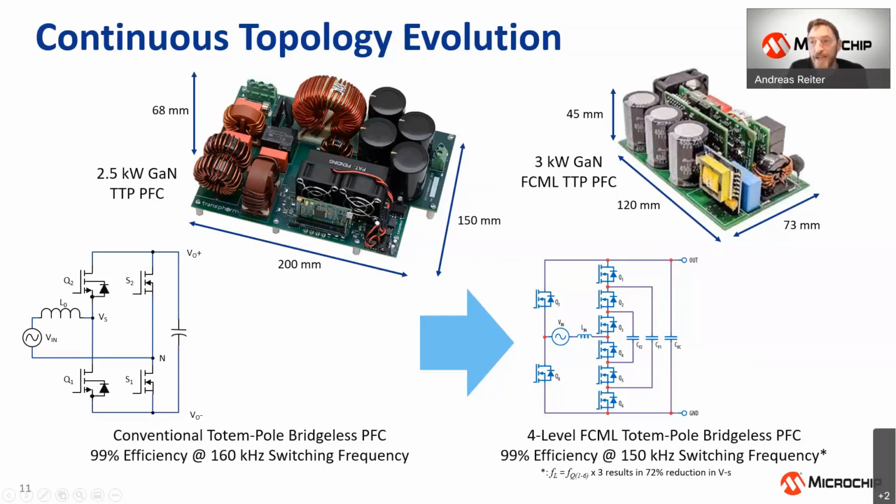Because everything shrinks down, you have different ways in how you can build up that converter. Here we have everything flat on the board, but here everything is getting vertical. So in this particular design, the access points we would need are just buried between two vertical PCBs, which are so close together that you hardly have any space at all to reach that point. So that is another example where things can really get tricky.